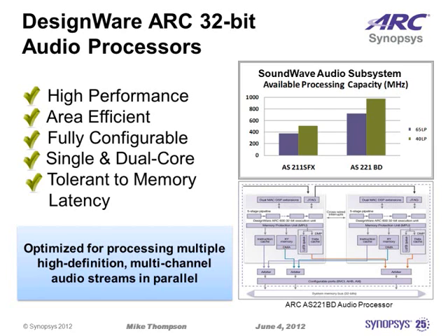They're both very tolerant to system latency, which can be important, especially in systems that implement audio and video, because video is going to dominate or is going to have priority over the audio. We've seen systems with as much as 500 cycles of latency. This is very tolerant. You see very little performance degradation, where with some of the other solutions on the market like HiFi or CEVA Lite, you see substantial performance degradation as the latency increases in the system.